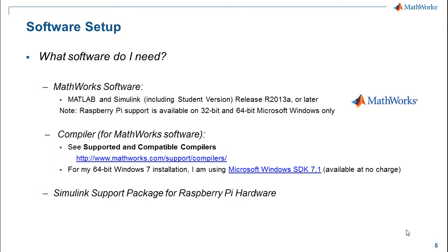We will need a compiler for the MathWorks software. In order to find one, there's a helpful link there that lists all the supported and compatible compilers for MathWorks products. For my 64-bit Windows 7 installation, I'm using a Microsoft Windows SDK 7.1, which is available at no charge.